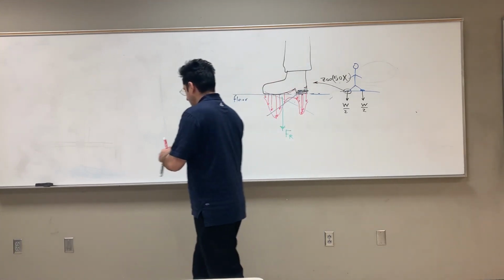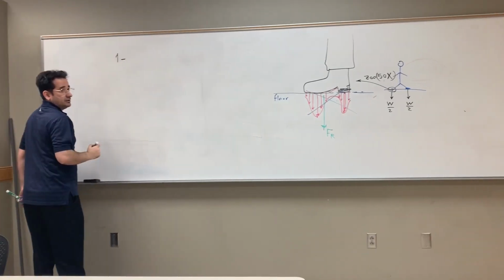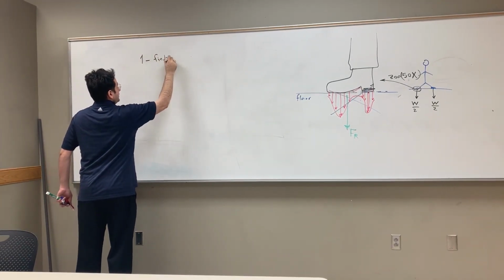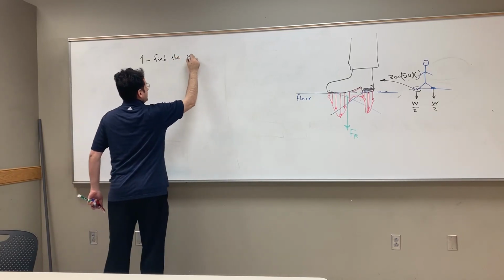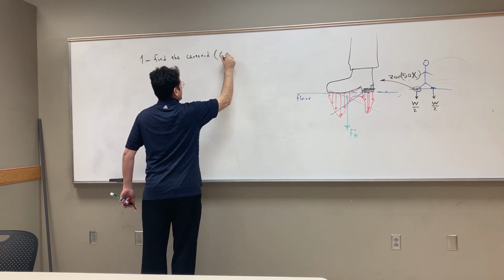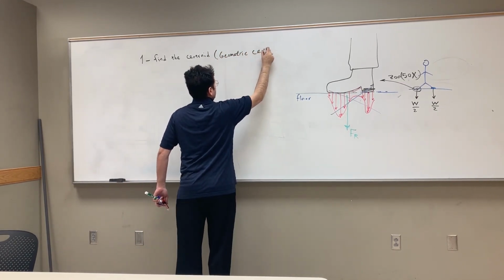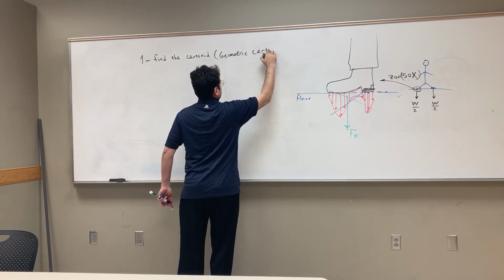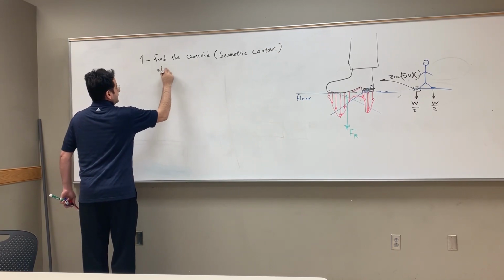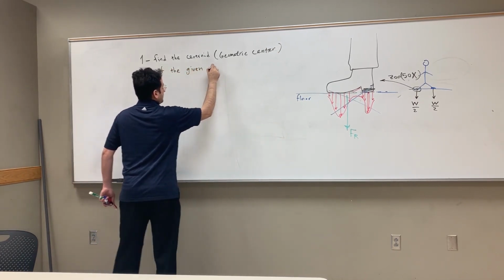If you have a distributed load, then step one, find the centroid, the geometric center, of the given distributed load.